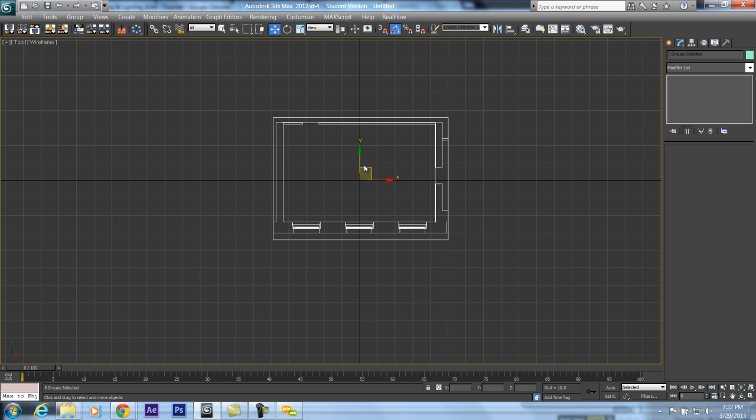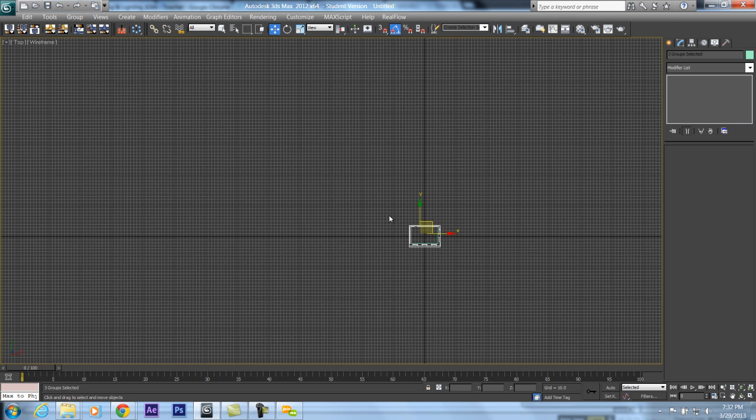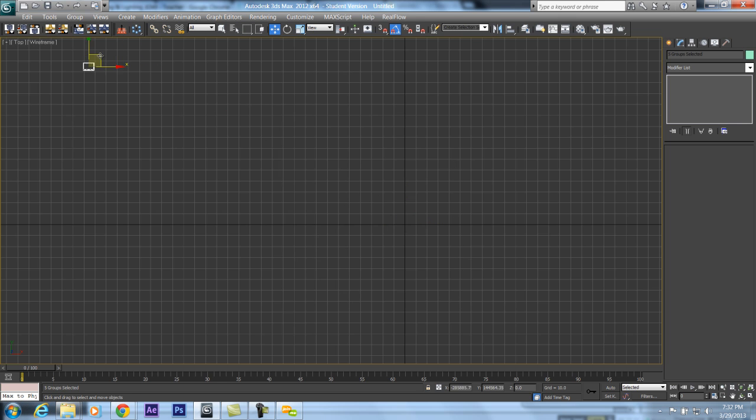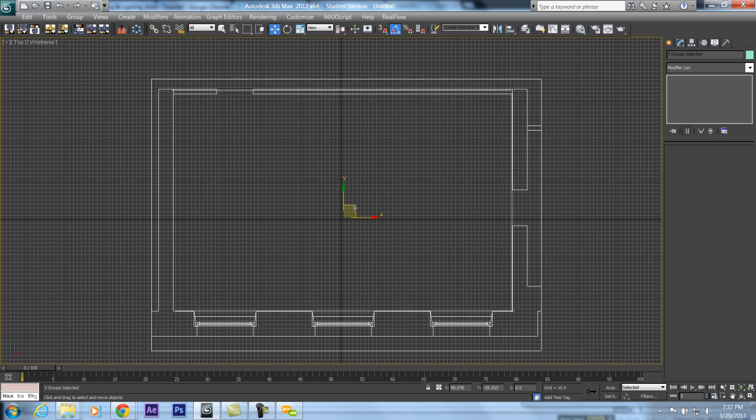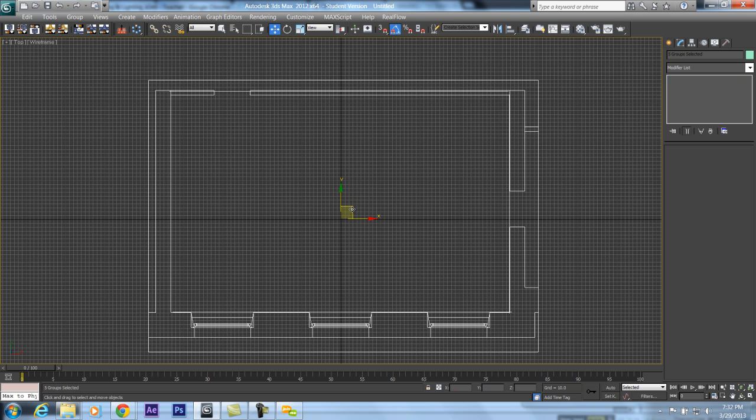If you place it somewhere else, really far, like here, your light will not distribute properly, and you might get errors such as far from origin and different errors that VRay gives in order to indicate that the file is far from the center, from the XY axis. So this is what you want to do. You want to place it always in the center in order to get really nice lighting distribution.